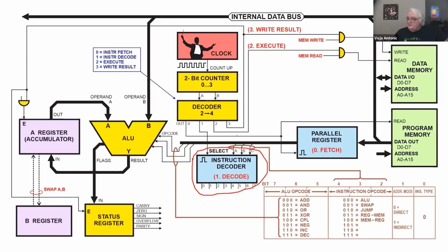One part of the program word is only 3 bits of the 8 bits in total. It defines which instruction is in progress, which instruction should be performed. If it's 0, 0, 0, then it's an arithmetic logical instruction. And in that case, it counts what opcode is here. Is it addition, ANDing, ORing, and so on?